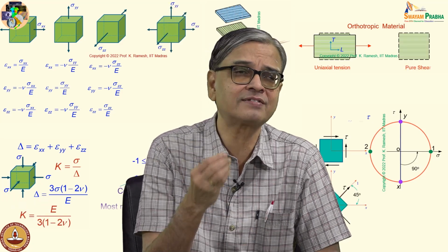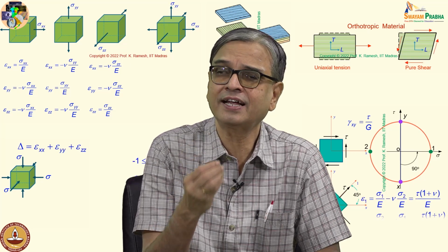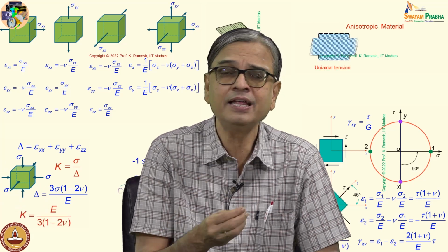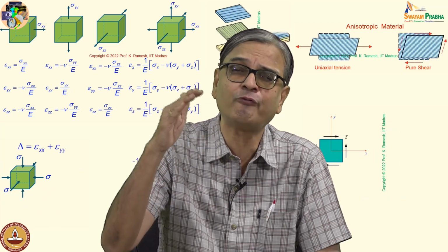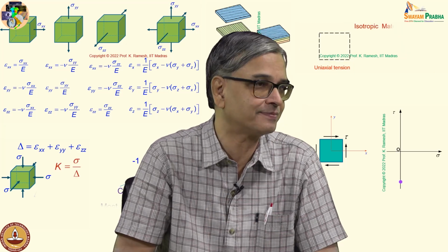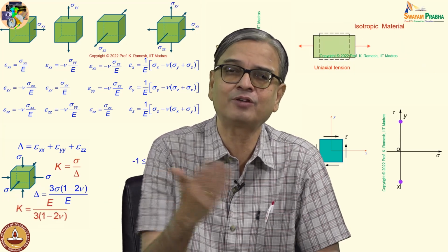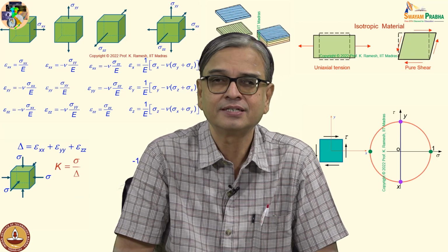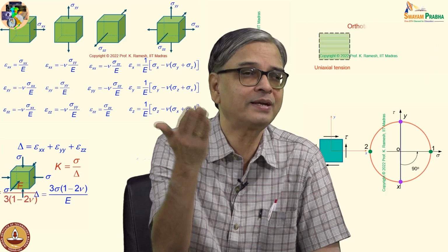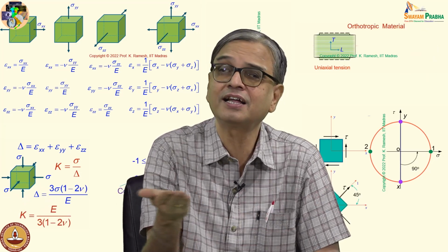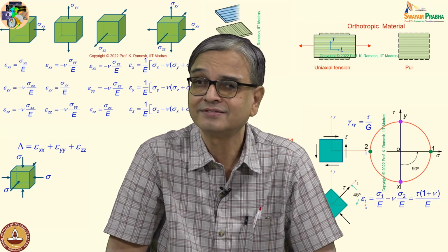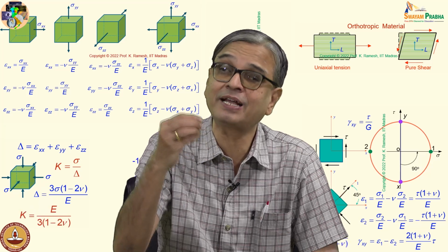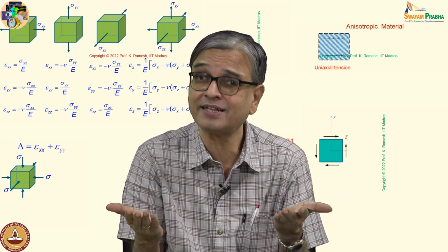And we have also seen with sufficient discussion, even though it is a convenient way to say small deformation, in reality, in many practical applications, we work under very small level of strain in actual loading. Because everything is dynamic, you are having only fatigue loading everywhere. If you come in your car, there are many moving parts. Even if you are sitting in your chair, you get up and then come back. That means chair is also experiencing a fatigue loading. It's a function of time, the load changes. So whenever the load changes as a function of time, the maximum load that I can apply is smaller and smaller, which you have seen by experience.